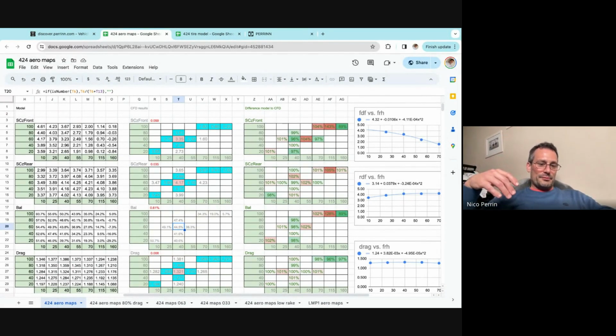And at that point, you have a bit more weight at the front. What you do when you build up speed is you are adding more vertical load at the rear than you do at the front because the balance is 44.5. So as you build up speed, you're loading the rear more than you load the front. That is giving you stability. It's building a little bit of understeer in the car.